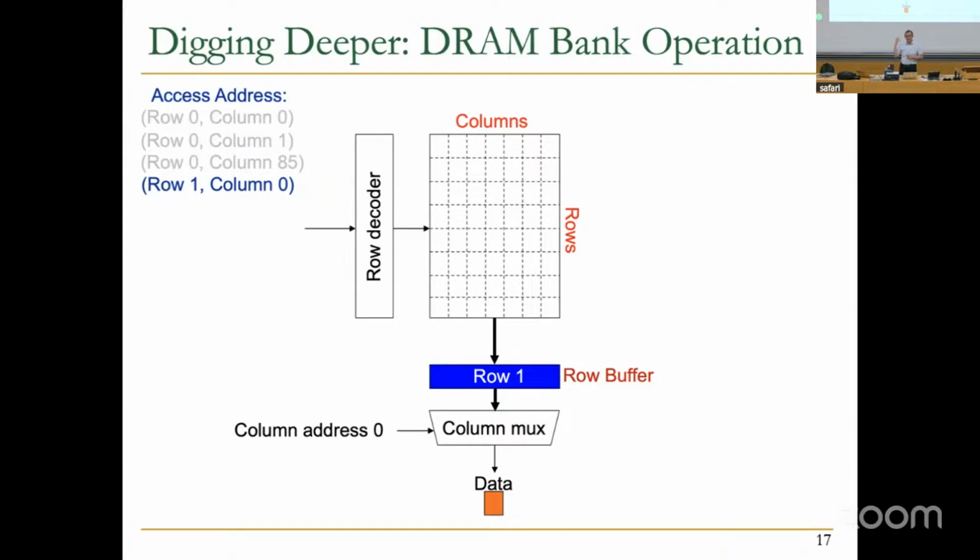Okay, this is actually exactly how a DRAM chip operates. We're looking at just a single bank over here. Ideally, of course, you would like to maximize the row buffer hits, right? This is affected by a lot of things: how you map the data into your banks, how you map the data into your rows, and what the access patterns from the processor are. So if the processor is always sequentially accessing data and the data is sequentially mapped in the row buffer, that's good. You get a lot of row buffer hits, like I explained.